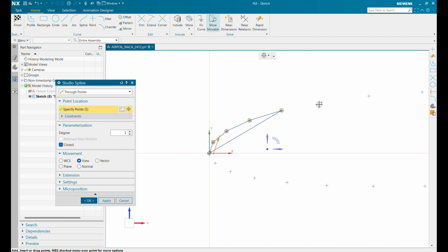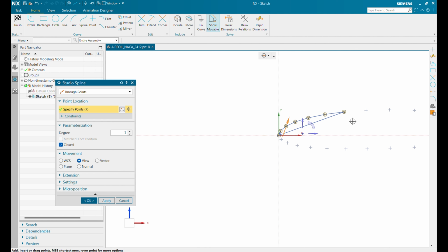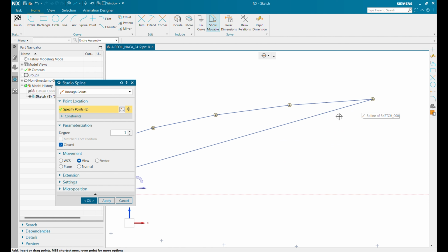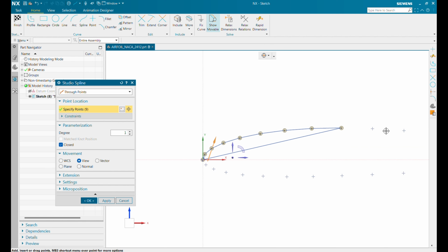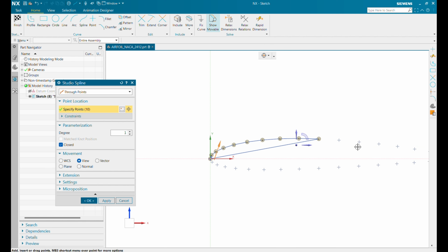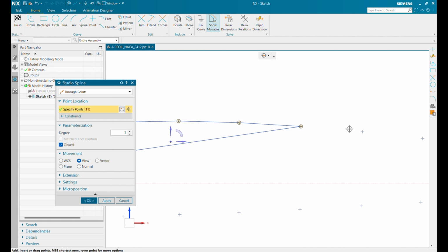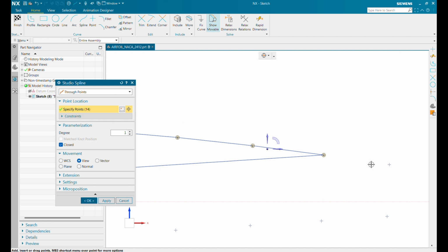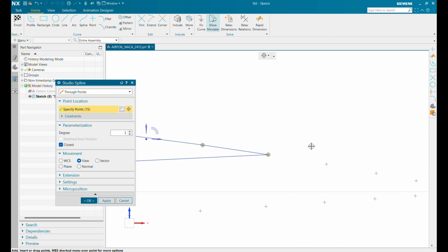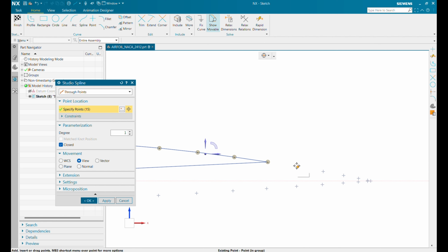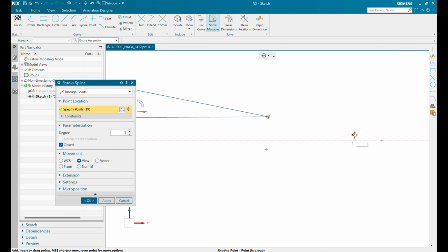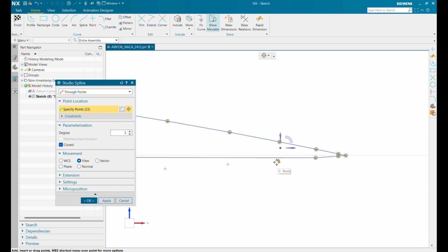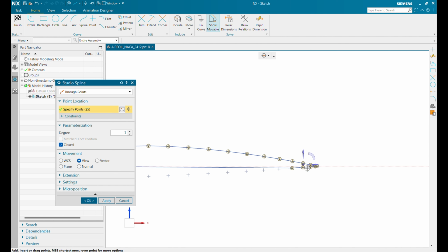And you don't need to have multiple clicks now. All you need to do is select all of these different points, and the spline will connect them automatically. And also you see we've got this thing called degree, which is the method of connecting the different data points. If you choose degree as 2, it will make a parabolic connection. If you leave the degree as 1, it'll be a straight line, and so on.